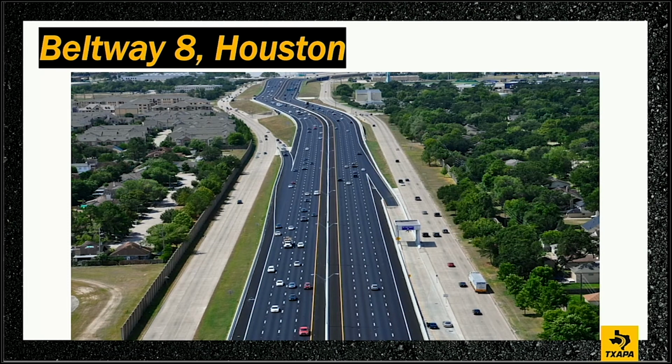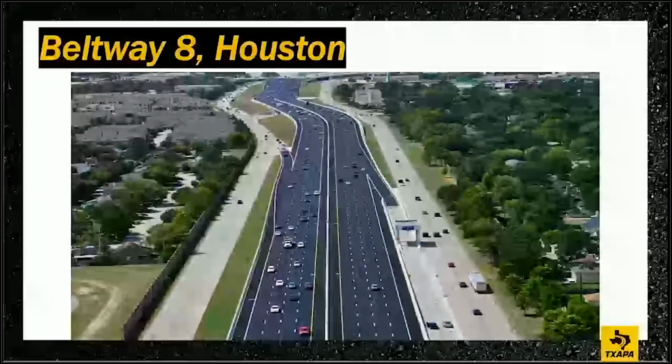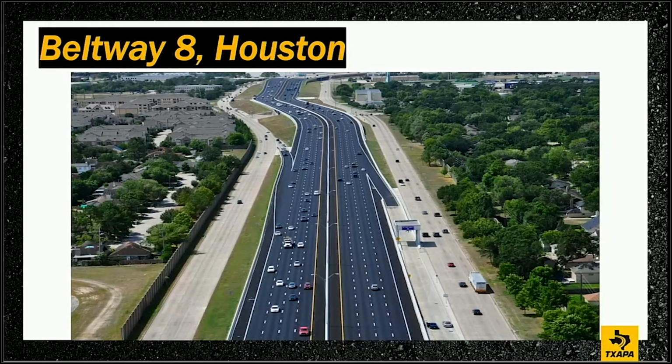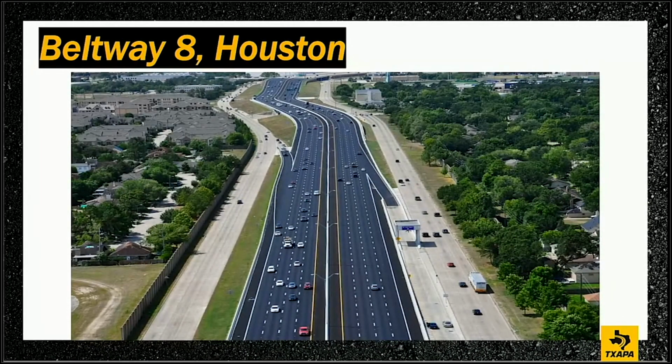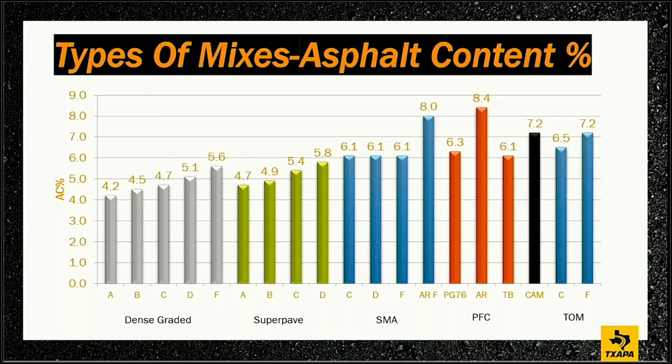There you go, it fixes it. Just saying. And if you want concrete to ride smooth, put asphalt on top of it. So again, design engineers, remember that. It's okay to put asphalt on top of concrete. Absolutely. If you want it to ride smooth and be noise reduced, just do asphalt on top of concrete. It's the Oreo method.